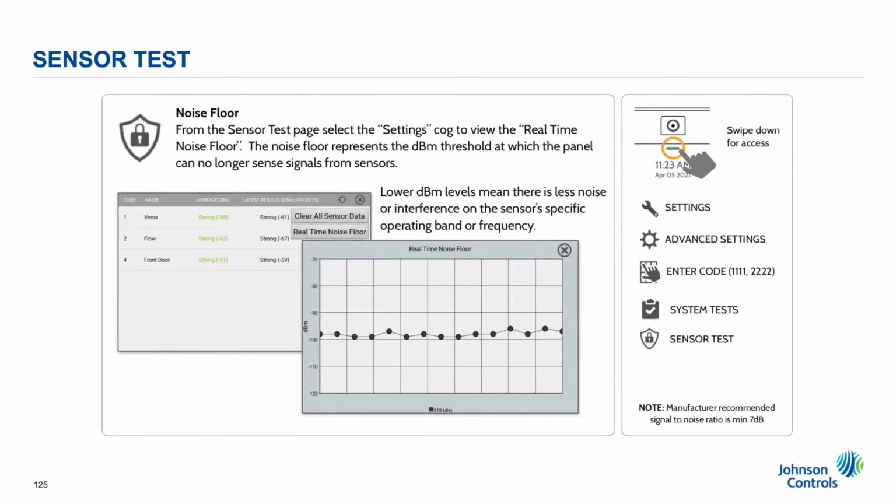For a more detailed view, each sensor can be plotted on a graph where they are measured against the ambient RF noise floor. This test works for all legacy SRF frequencies like 319.5 MHz, 345 MHz, and 433 MHz. Get it right before you leave the home.